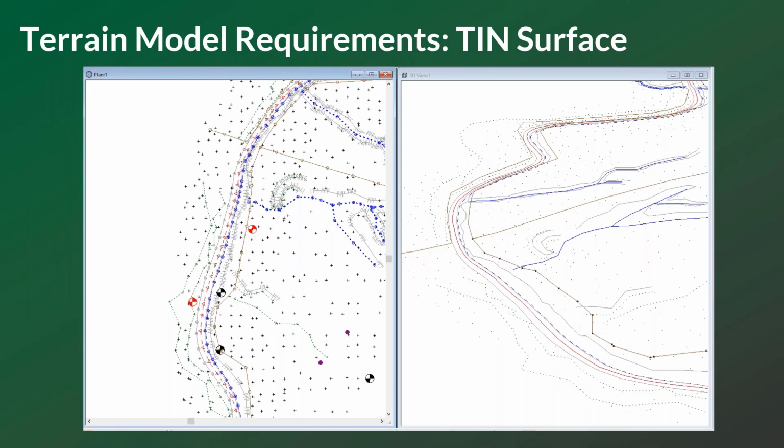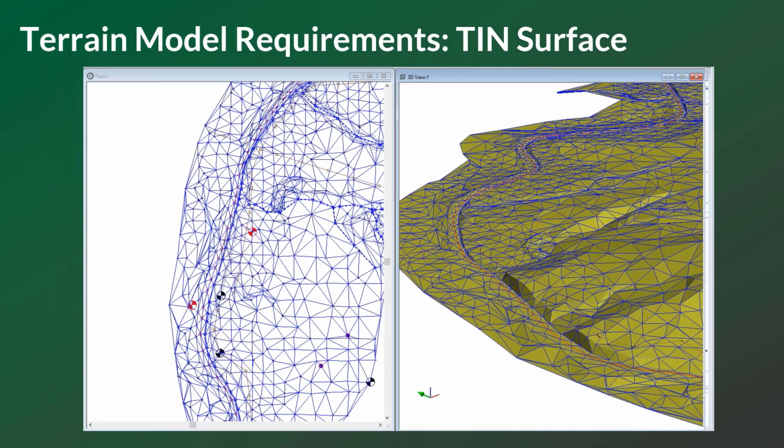We just have points. So Matt went up, used our terrain calculation dialog, and he was able to generate something called a TIN. A TIN stands for a triangular irregular network, and this connects the points with different triangles. These triangles then can form a full surface. This view that you see here is not typically shown. However, you can enable it pretty much at any time if you wanted to see how your TIN's being created.